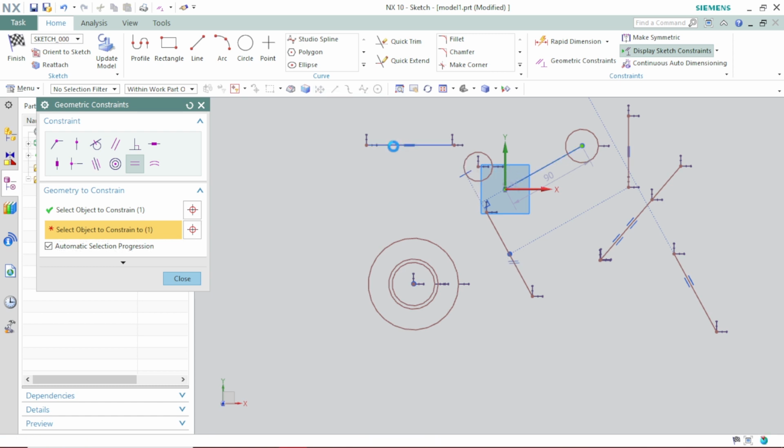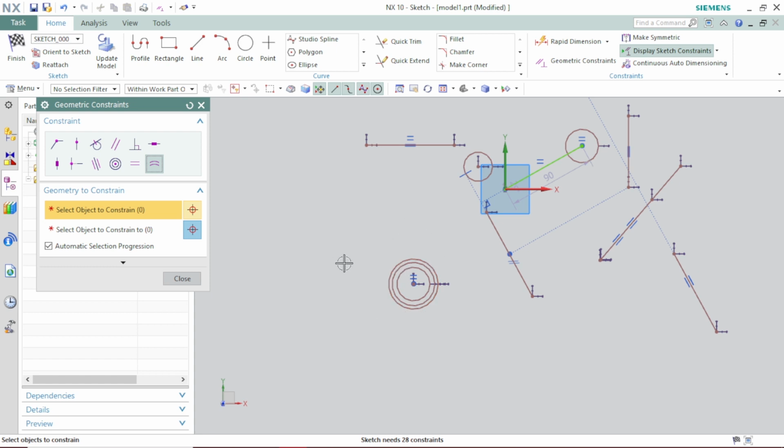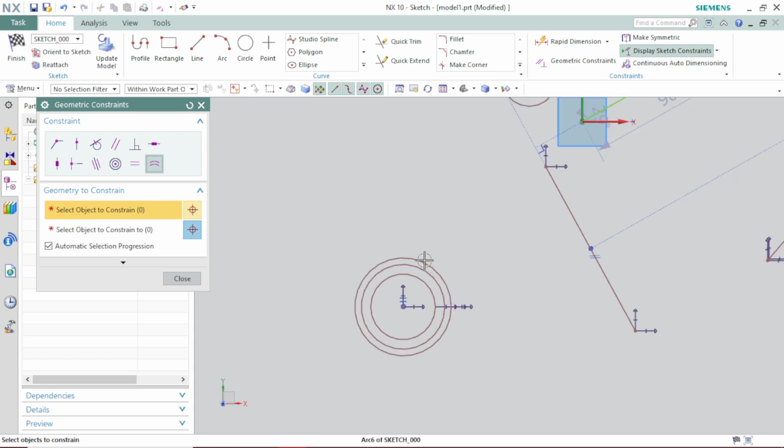Let's suppose select this line, so it gets bigger, it will get up to 90 mm. Likewise, if you want to make equal radius, you can just select, let's suppose this one and this one, so your second selection has been selected and got equal radius.